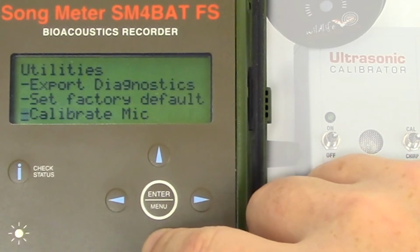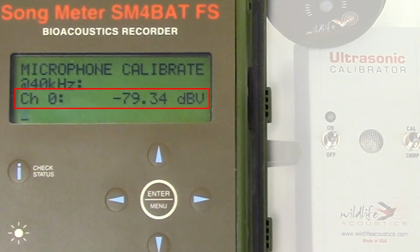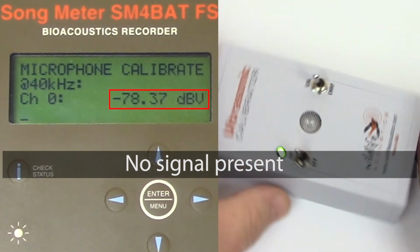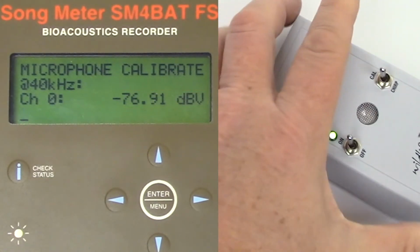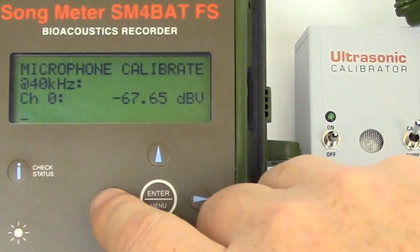The next item under the Utilities menu is Calibrate Mic. The display shows a real-time output from the connected microphone. Specifically, the display shows the microphone level at 40 kHz frequency. I'll place the U2 microphone onto an ultrasonic calibrator. The calibrator emits a 40 kHz tone. I can't hear this signal, but you can see the U2 microphone is picking it up with no problems. Now we have confirmed that the U2 microphone is connected and working properly.